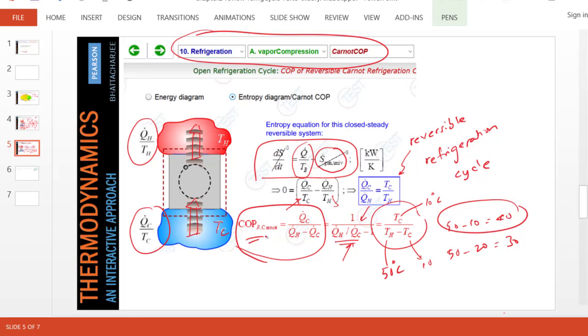Of course, this is for an ideal cycle, but a real cycle kind of mimics the ideal cycle. Not just that, if you increase your cold temperature, your cooling load will go down, because if the room is less cold now, the heat leaking into your room will go down. So you save both ways. So it's important to emphasize the importance of Th minus Tc on a refrigeration cycle.